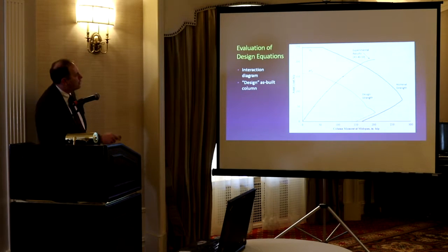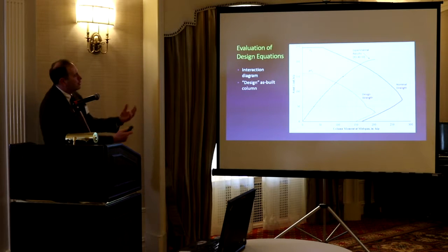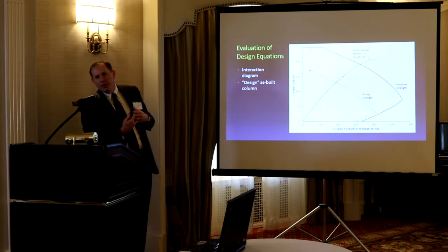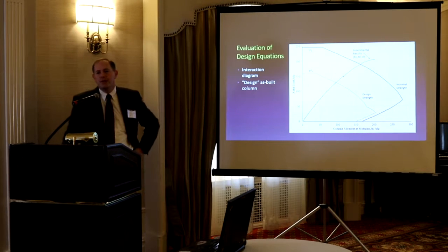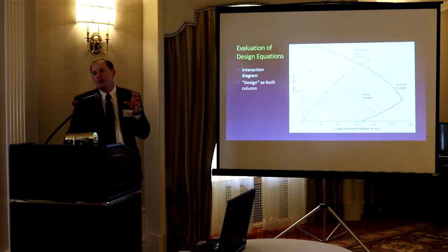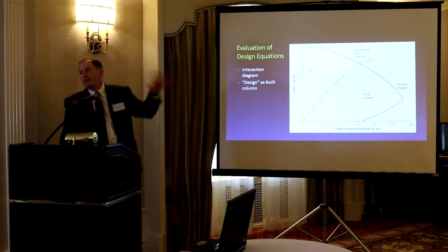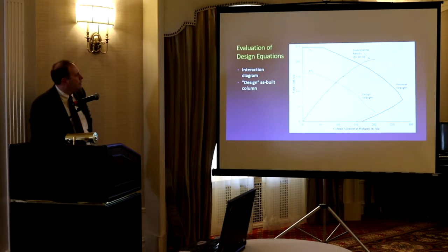This is the nominal strength curve. This is the design strength. So this is where ACI would bring us in with our phi factors for the safety. Experimental results, we're looking good. I mean, in all cases, our tests fail beyond what ACI would allow you for design past nominal. Okay.